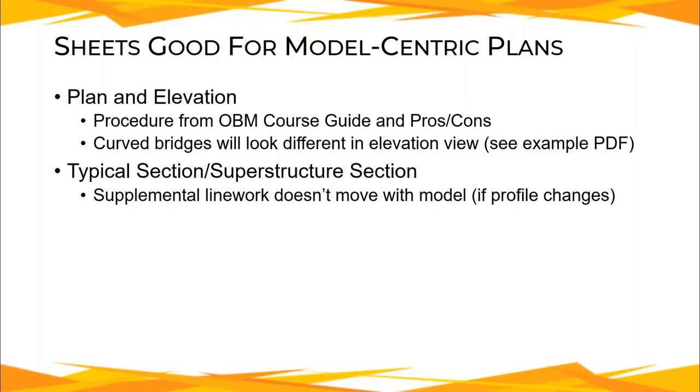One downfall of that, though, if you want to call it that, would be that supplemental line work doesn't move with the model, like if the profile changes. Normally you wouldn't detail anything in great detail so early on where the profile is going to change. But let's say you did, or let's say there was a profile bust and then the profile had to change late in the game, and I had drawn in all my little dots for all my rebar and extra line work, hand drawn in a drawing model to supplement the section view that I created from the 3D model.